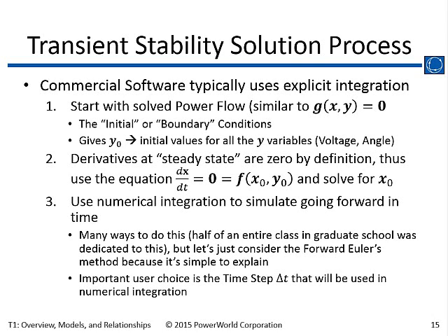So I think the PS in PSLF is positive sequence load flow. PowerWorld uses a positive sequence model, and that's true in transient stability as well. The way we model unbalanced conditions is just from a fault condition. When you put a fault on the system, like a single line to ground fault, you use a compensation technique where you treat that fault as if it were just in the positive sequence value, but the current takes into account the negative and the zero sequence from the fault.